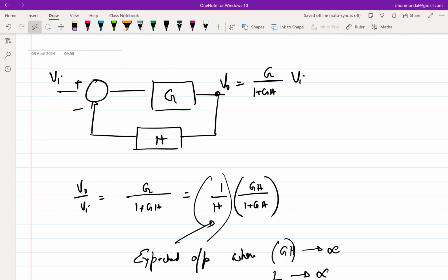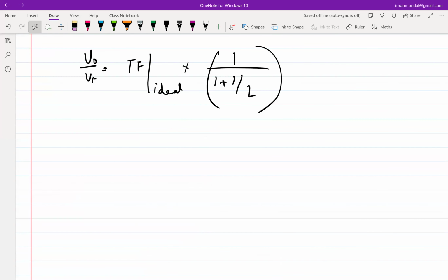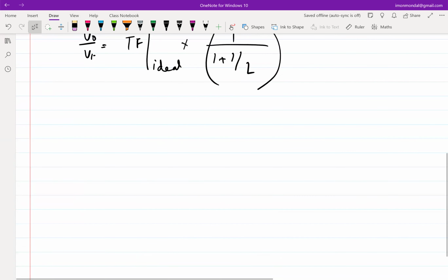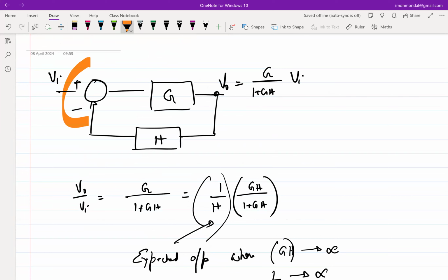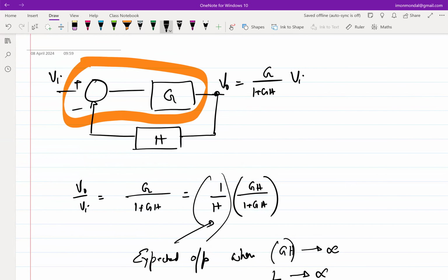So now, the other thing that we did in the last couple of lectures was to replace this entire block diagram with a transistor, and we understood that this contraption is essentially a summer followed by an amplifier, right? And again, for the next time, G need not be accurate. All you need to ensure is that G is large. So we know how to make an amplifier with a large gain as long as it meets certain constraints.